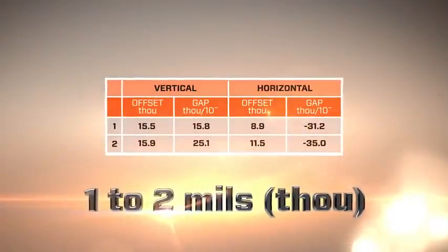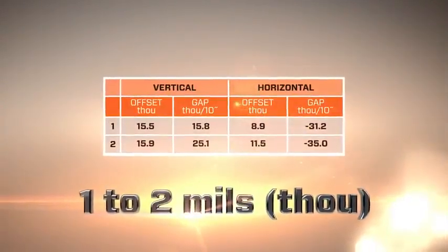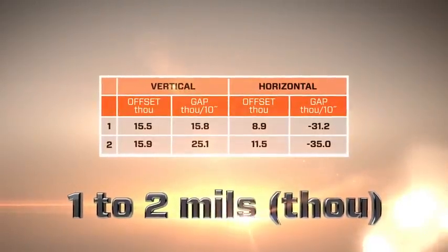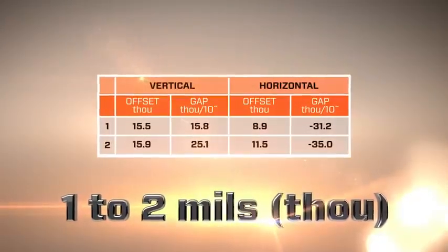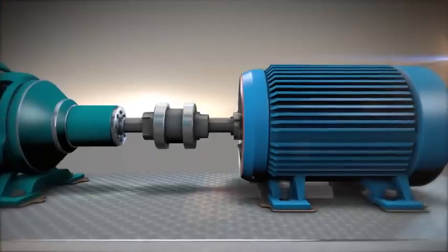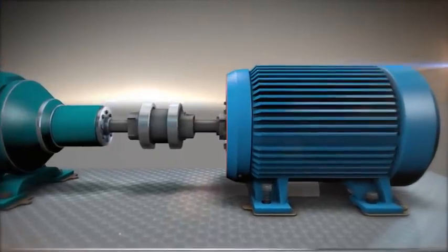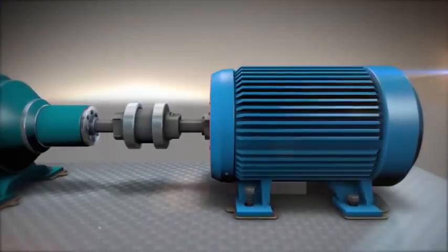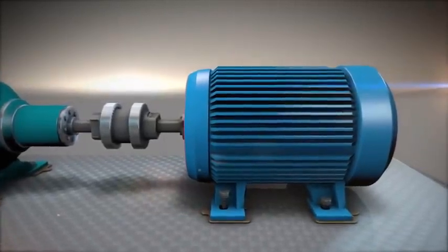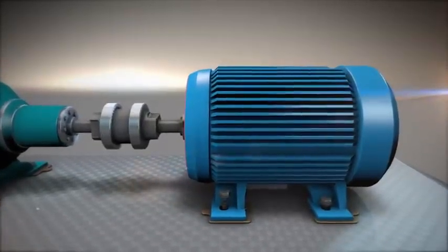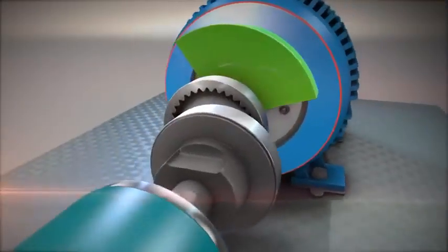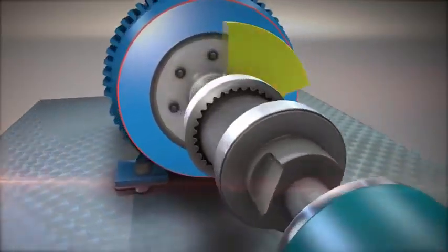Once rough alignment has been performed, the results should be no more than 1 or 2 thousandths apart, which is not the case in this example. It makes no sense to proceed with the alignment until and unless repeatable readings have been achieved. If repeatability is poor, there may be several root causes to consider, such as loose components, worn bearings, loose anchor bolts, and vibration from nearby machines, among other causes. Once the culprit is found and addressed, take 2 new sets of readings to establish repeatability.